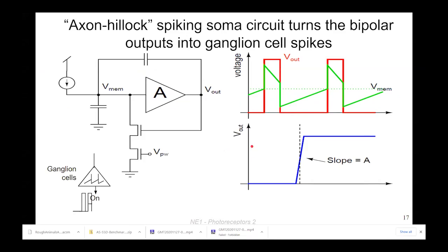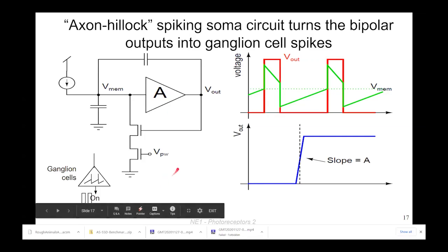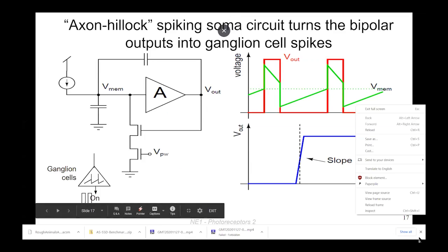And so the neuron circuit is incredibly simple. It has a drawback: if this is a real inverter here, it burns a lot of power as you're crossing the threshold. So you have to use static inverters there, not the traditional inverter, instead of using the inverter that looks like a digital inverter.